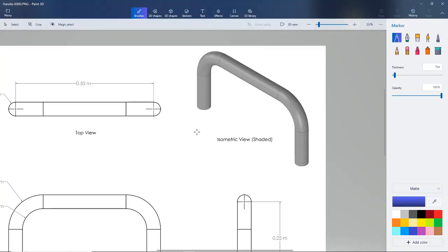That makes sense. Okay, consider this handle. Are you considering it? Liam, are you fully considered? I am fully considering this. Okay. If we wanted to try to get a handle on modeling this, we would have to approach it from a couple different directions. We could break it into 3 linear extrusions if we wanted to, and then 2 revolved extrusions, but there's an easier way. There is. That easier way is the swept extrusion.